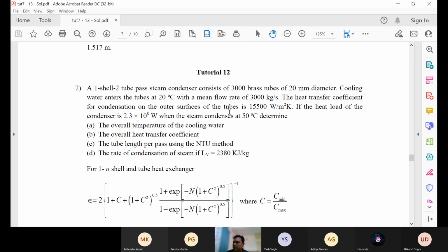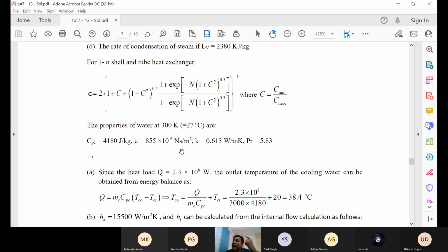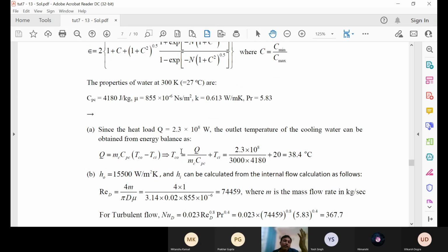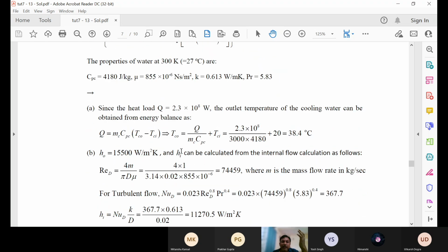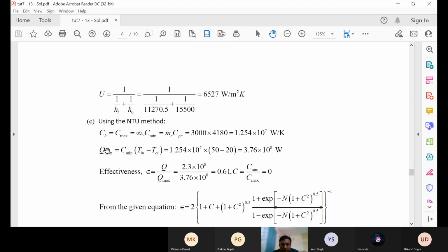But what about MHCpH? There is no specific heat when you are condensing. When you are condensing a fluid, there is a latent heat of vaporization, and latent heat of vaporization is considered as an infinite capacity. Because of that, MHCpH, which is nothing but Cmax, will be infinity.